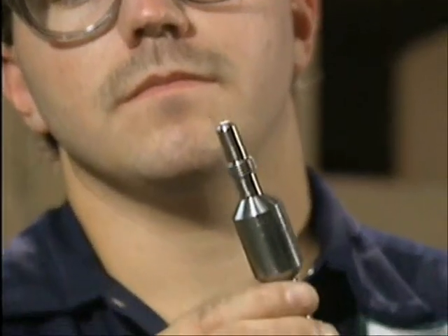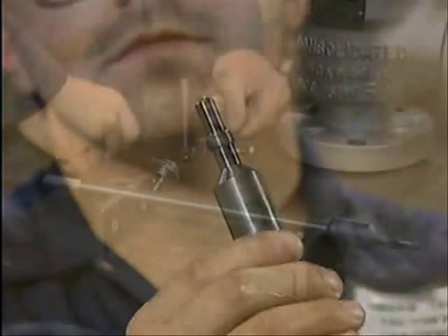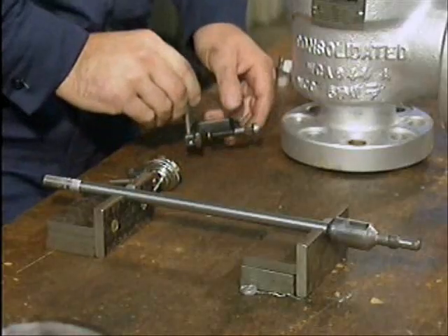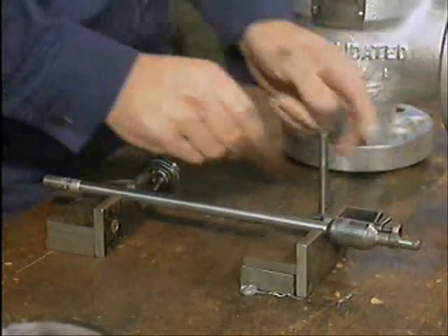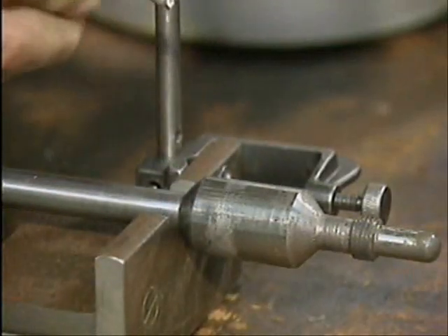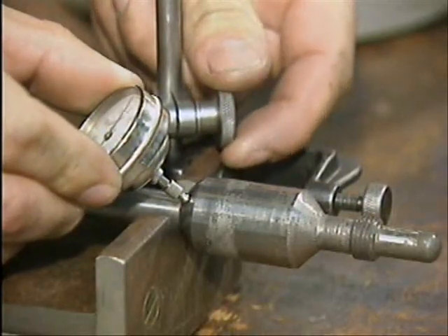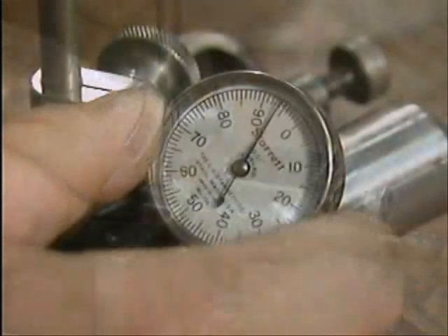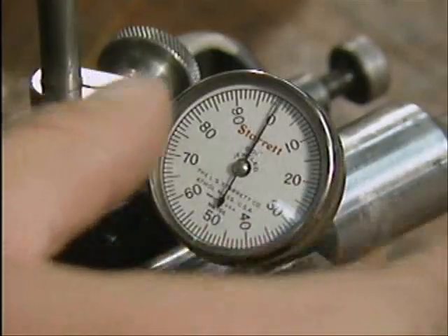A common way to test a stem for straightness is to take a runout reading with a dial indicator that's mounted on a magnetic base. With the stem set up on a pair of V-blocks, place the dial indicator beside the stem and secure the dial indicator's base in position. Next, press the stem of the dial indicator against the surface of the valve stem until the dial indicator's stem retracts about 1/4 of its length. Set the dial indicator to 0 to provide a reliable reference point for the reading.